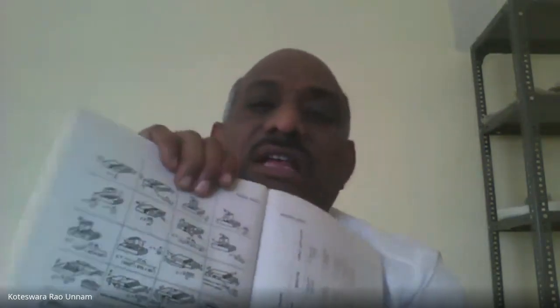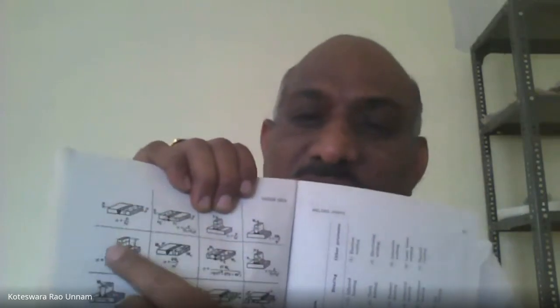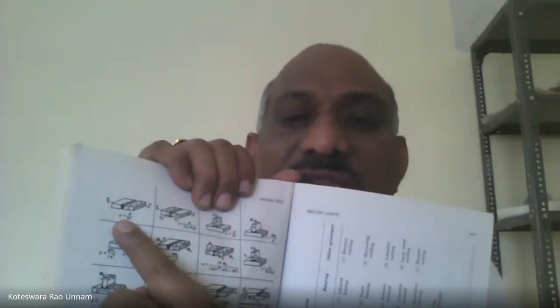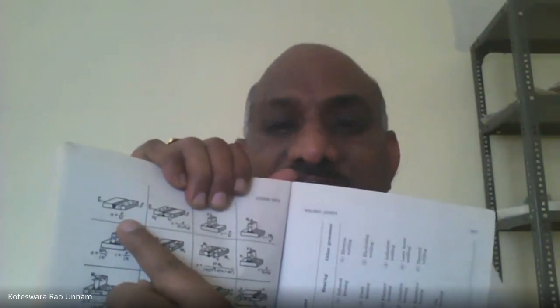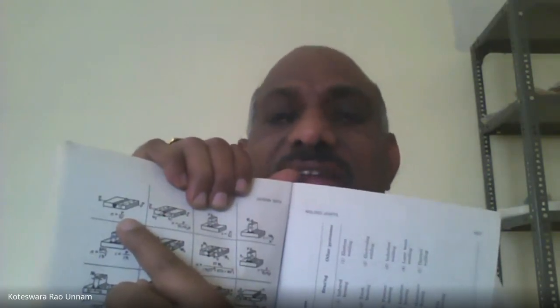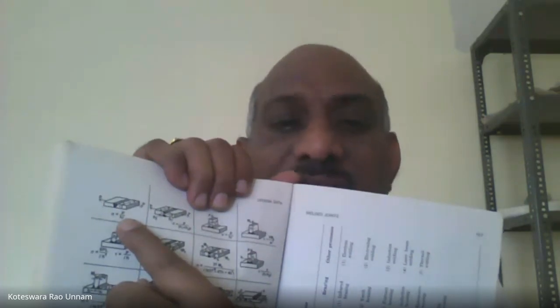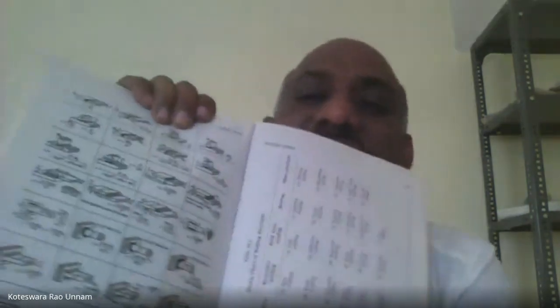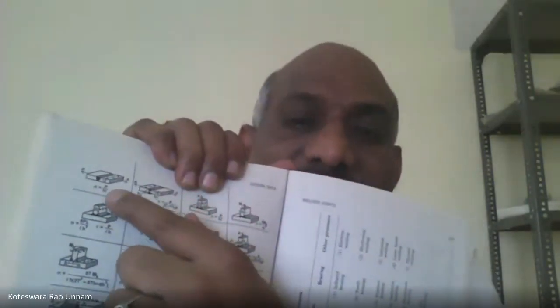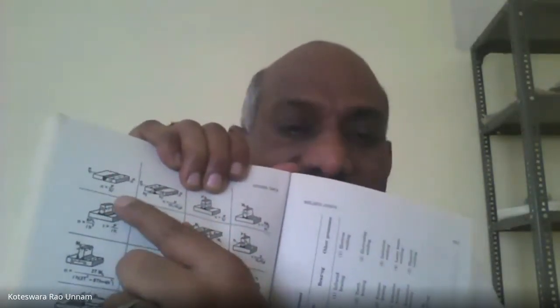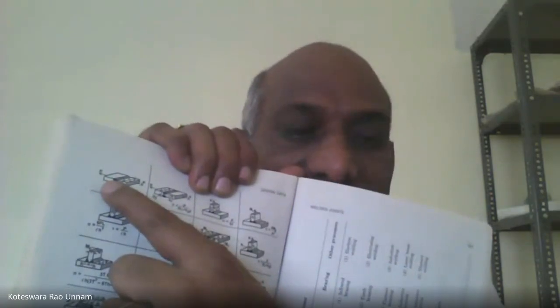Now that I know the terminology, if I come to this picture here, this is our single V butt joint. Below the picture he has given the formula for sigma. Sigma is equal to P by HL, but we are taking it as TL. So here he has taken H in place of T. That's what he has given in the description also. At the bottom he has given what these parameters are: what sigma is, what L is, what H is, and what P is.